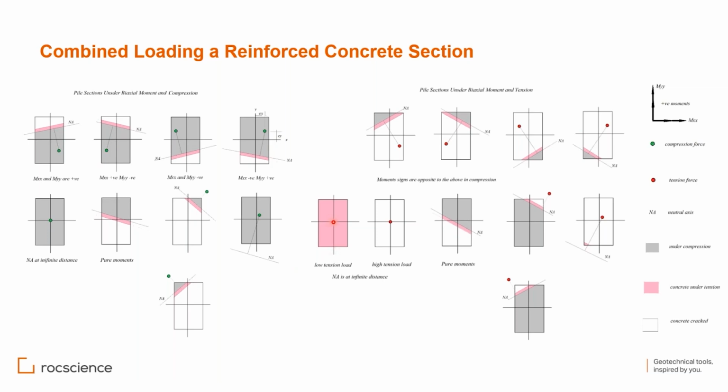So if you have a low tension, the whole section is not cracked, but it is under the tensile strength of the concrete. While if the tension increases, the only thing that will take the tension is the reinforcement, which is not shown here. So the whole concrete will be cracked. This is just to show you how the concrete behaves in the section under different loading conditions.